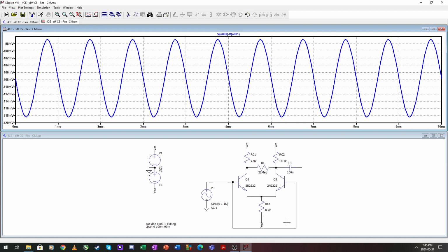Okay, so using resistors for single-ended is bad. Using them in differential mode, you will get the offset that you need to cater for, and you will get a common mode signal, but it is not that large as a single-ended output.